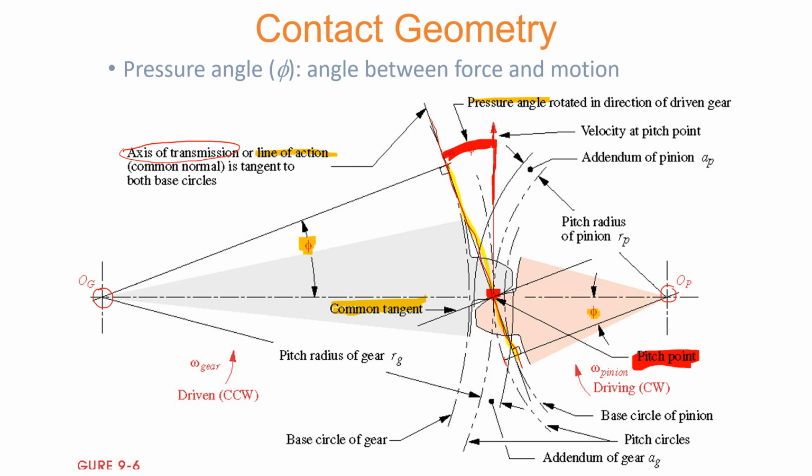Now, on top of that, you can see some terminologies which are kind of alien, like addendum over here or over here. This is not a very complex terminology, in fact. The distance between the base circle, like over here, and the pitch circle is going to be indicated as the addendum of a particular gear profile. So with this realization that you now have the necessary contact geometry cleared, we can move on.